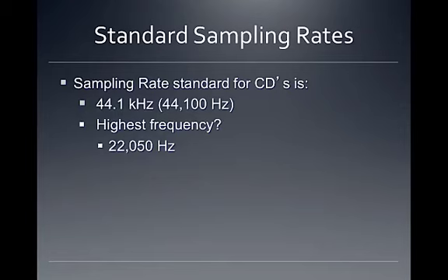And it all comes down to this idea of aliasing, where if the A to D converter hears sounds above that Nyquist frequency or hears sounds above 20K, which it will, it's possible that you might have a microphone that can capture sounds above that.